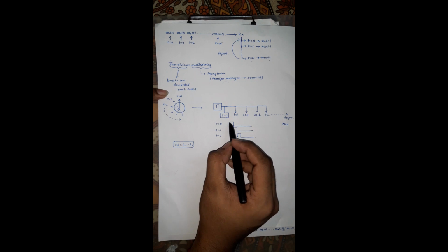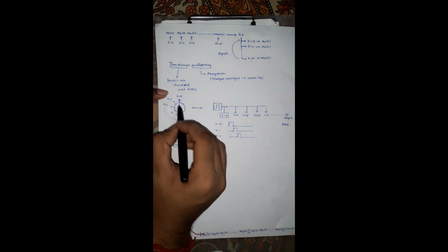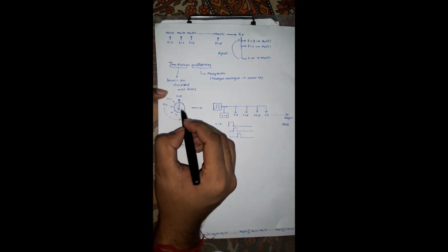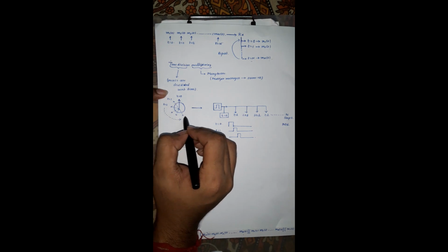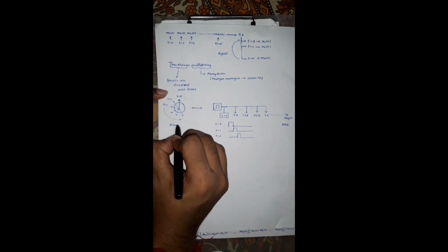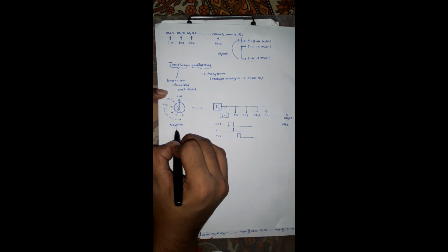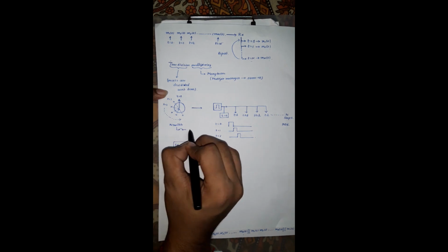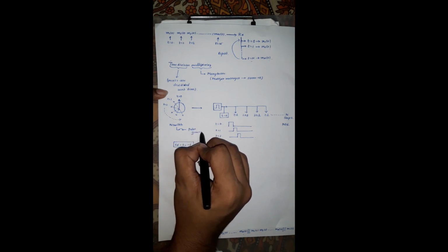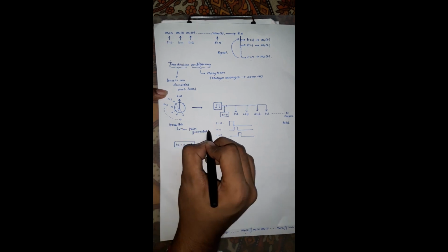Now what is happening over here: as the positive pulse is applied in this commutator circuit, there is a switch in the commutator circuit, and there are a total of n number of switches. The n switches are connected to the pulse generator, that is a delayed pulse generator, where the pulse generator is delaying the pulse sequentially by n number of time delays.